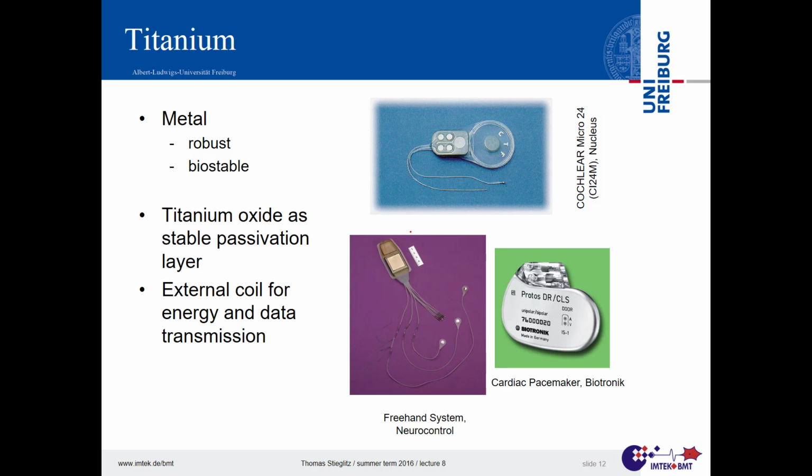That's the beauty. It's the same what happens in standard iron. But we all know if we put iron outside in the rain, it's not that stable. And the difference between iron and titanium is that the volume of titanium oxide is closer to the volume of titanium than iron oxide is to iron. And if the volume ratio is between 1 and 2, then it stays stable.